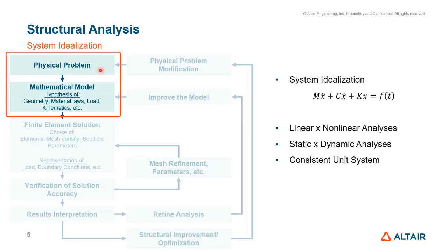Exemplifying here a structural analysis where we've talked about the suspension system. We have our physical problem, which is mainly my suspension system, where I want to evaluate the response due to some inputs such as the cornering or the braking force, and this will be my physical problem. And for that, I can build a mathematical model. As an exemplification here, Newton's law, where it takes into account the acceleration, the velocity, and the displacement. This equals a force that varies along the time.